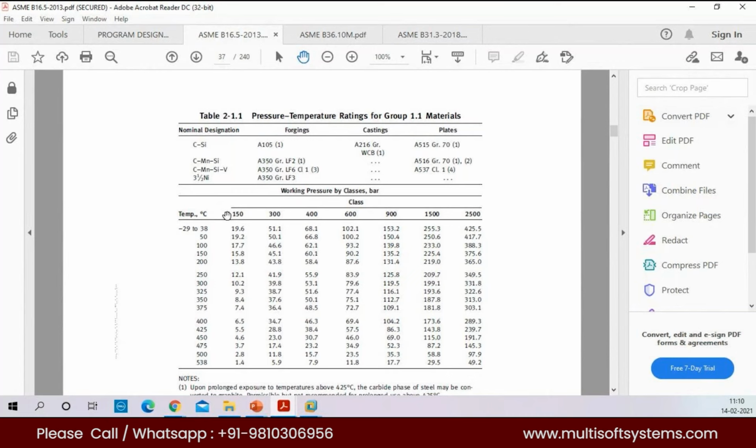Even for just water, with no temperature concern, but if it's highly corrosive water or any such fluid, then we go for stainless steel. There is no limit saying that only after 530 degrees Celsius we go for stainless steel. Not like that. Sorry to interrupt.